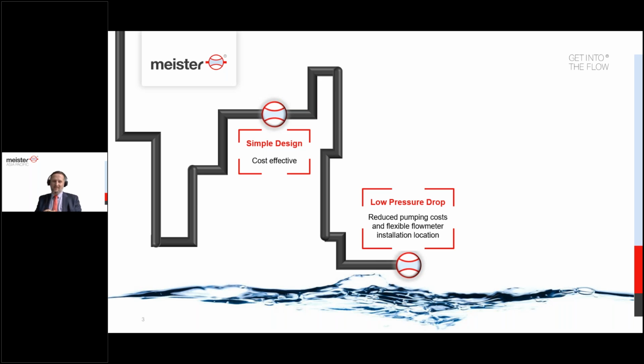So here we have to see and compare our flow meters to the various different other types of flow meters, where other types do not have anything in the pipe at all, would allow a free flow of water. In that case, the variable area flow meters do not have this specific advantage. But then there are again other types of flow meters. Let's say the volumetric gear type, some impellers, turbine flow meters could have then a higher pressure drop. So here it's a relative advantage to those kind of flow meters.